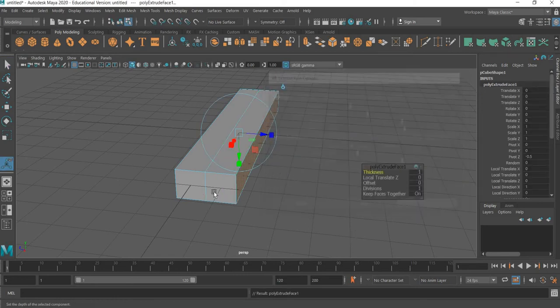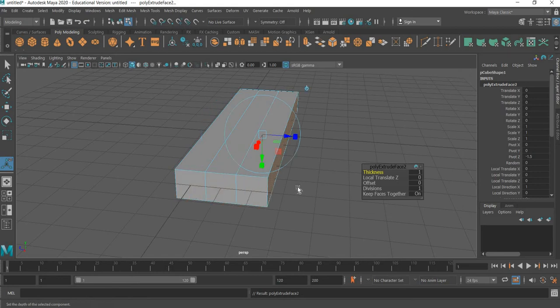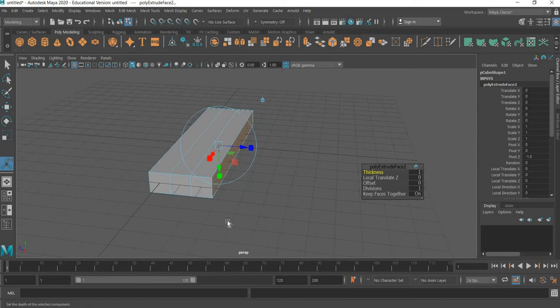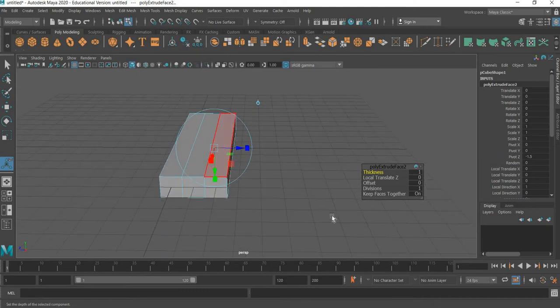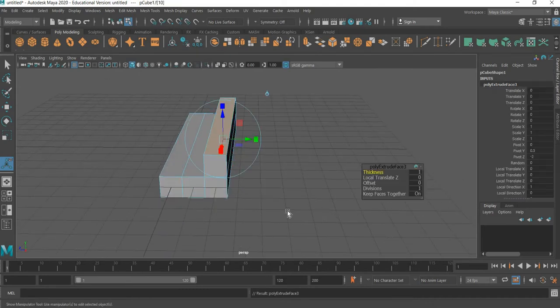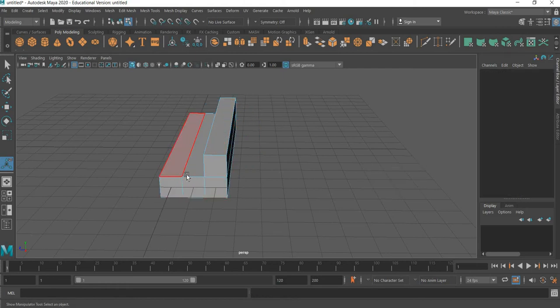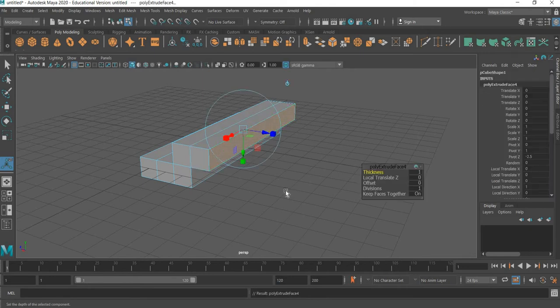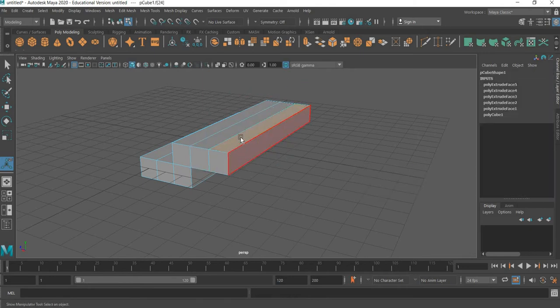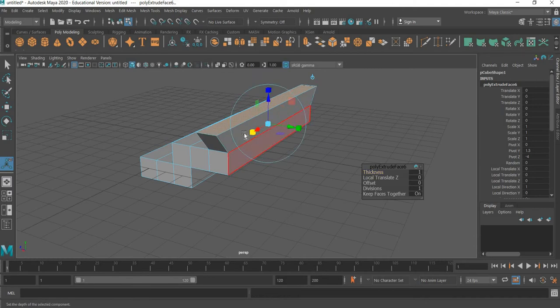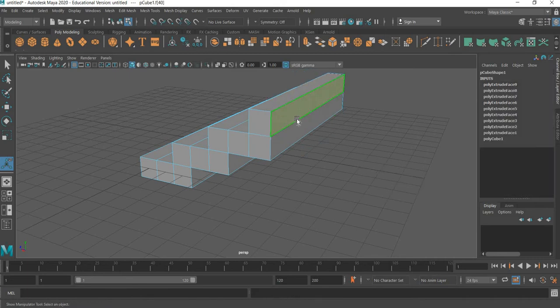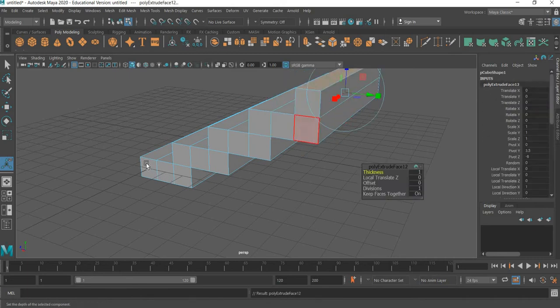So we'll apply it, and this will be the width of the stair, and I'll hit the G key to repeat the previous command, and we get the height here. So I'll G it. So 2 risers, 1 height. Then we'll hit G again, select this, G, G, G, G, G, G. So we'll create 10 steps.